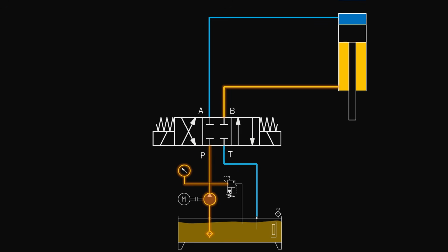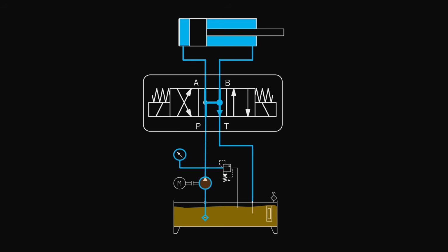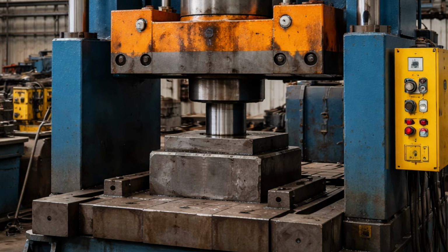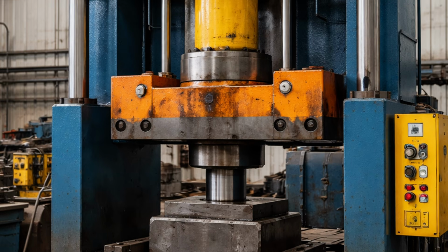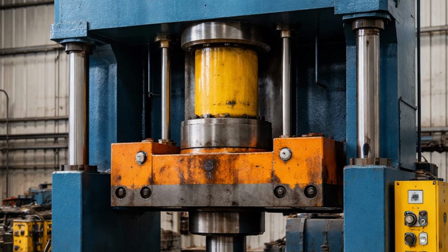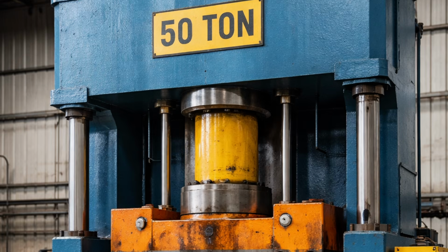So as we have seen, there is no single best hydraulic circuit. Everything depends on operation and operating condition. If the system operates at low pressure, no heavy load, and the cylinder creep is not a problem, we can use these directional control valves directly as per the system functional requirement. But if the system operates at higher pressure, like a hydraulic press, there are two things.